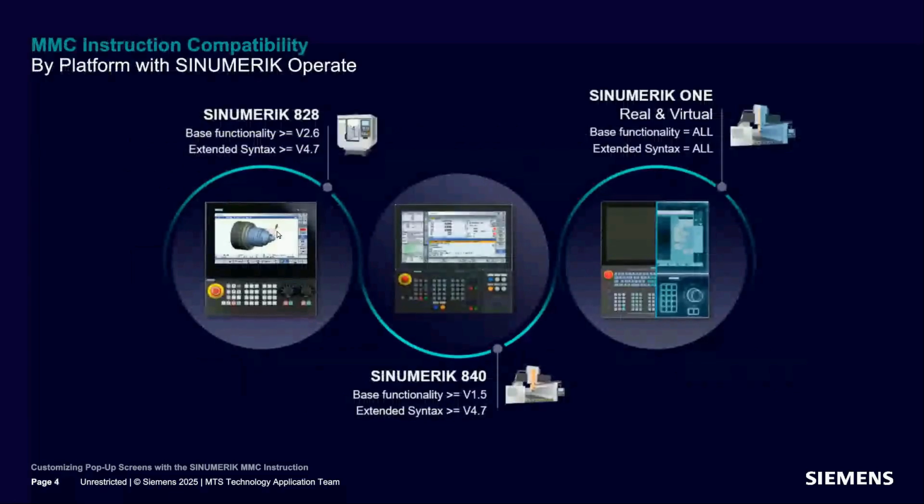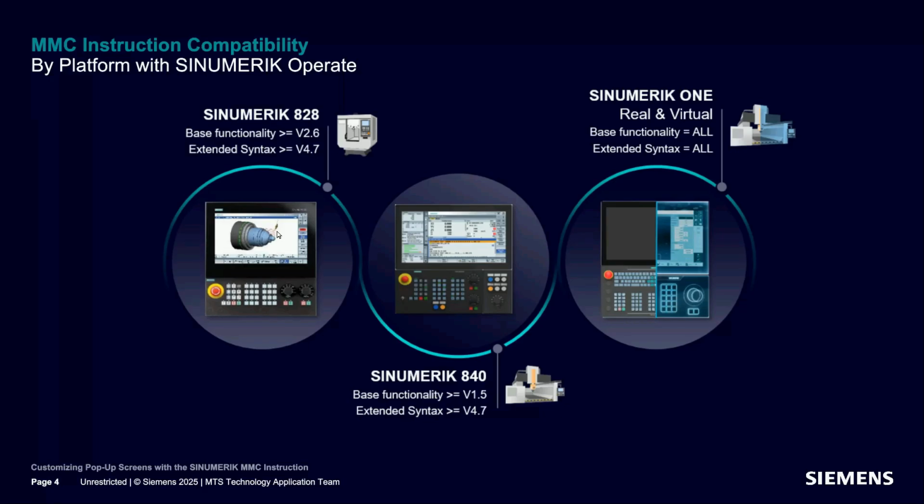Now, you may be curious to know, does your system support the MMC instruction? If you're using SINUMERIK Operate, the answer is almost certainly yes. If we look back at the 828 control and look through all the part programming manuals that we have, I started seeing this MMC instruction come up around version 2.6. With SINUMERIK 840, I saw it come up in the 1.5 documentation, and it's existed for the whole life cycle of the SINUMERIK 1 so far.